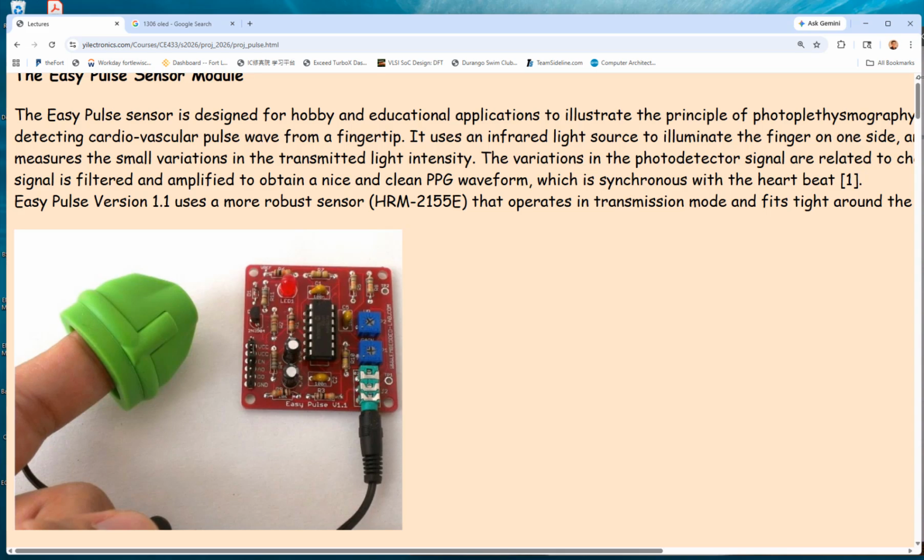So in that case, what about the power supply for this guy? It's 1.8 volts, right? Does it affect anything of your FPGA power supply? No, it's not a common power supply. You have common ground, but not common power supply. The power supply for this is separate from the FPGA's power supply. Your FPGA is powered by the USB port, 5 volts, and it's being regulated to 3.3 volts. However, the designer of the ADC decided to use 1 volt as a range for the ADC, which is fine. It's very common.